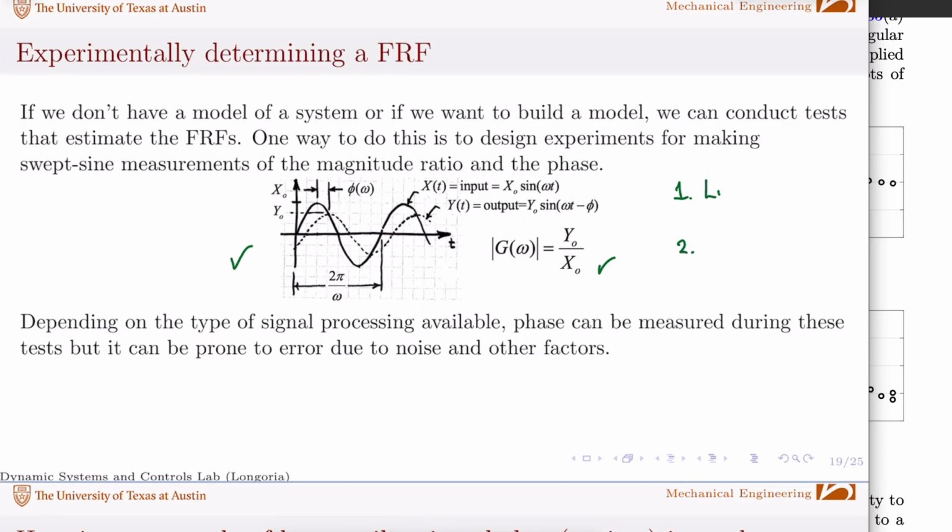often we talk about the linearity of the system, and certainly that's the case. What that says is that if I put in a sinusoid with a certain frequency, what I get out is a sinusoid with that same frequency, with phase and amplitude change, depending on what your system's made of. You can always put a sine wave into a system that's not linear. If you put in a sine wave, you're not necessarily going to get out just a sine wave. You might get different frequencies because of nonlinear behavior in the system.